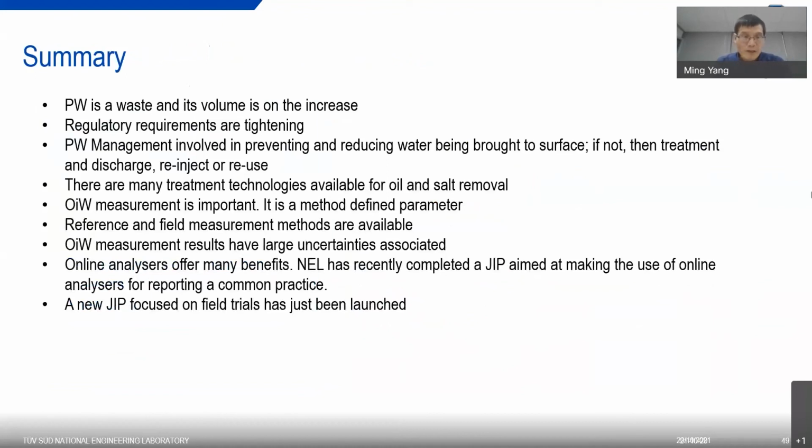When it comes to produced water management, we're looking firstly at preventing and reducing the amount of water being produced. We cannot always do that. Then we're looking at treatment, discharge, injection, or reuse. There are many treatment technologies, in two main categories: one to remove oil and solids, and the other to remove salt.